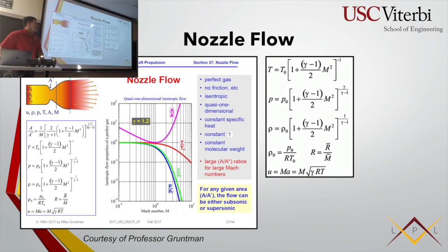And so this is back to that thing I was talking about at the beginning. You have a flow and you accelerate it, and you can relate your Mach number to a certain temperature using your stagnation properties here, your made up properties. So you use this equation,